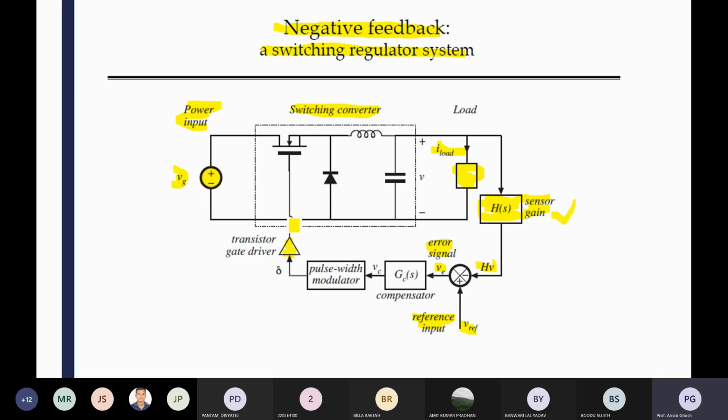So your control circuit is protected in two segments. One isolation is on your output side, another isolation is on your driving circuit side. Two isolations are there, so that the fault should not go there anyhow. Ground isolation is mandatory.